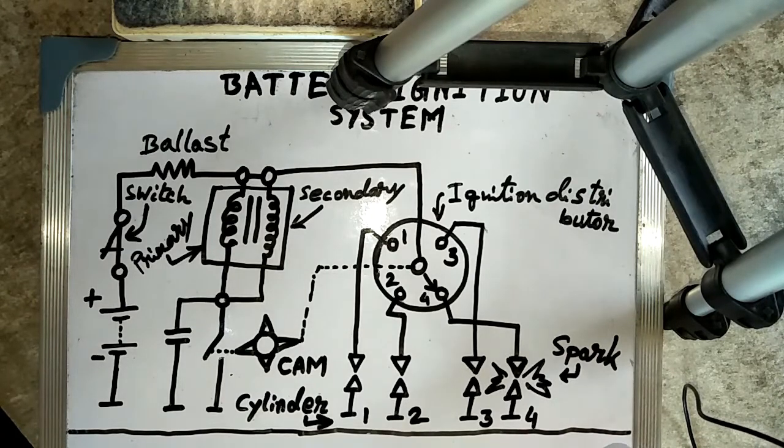Okay, if the primary circuit is closed through the contact breaker contact, a current flows. That is called the primary current, and this current flows through the primary coil, which is wound on a soft iron core and produces a magnetic field in the core. A cam driven by the engine shaft is arranged to open the breaker point whenever the ignition discharge is required.